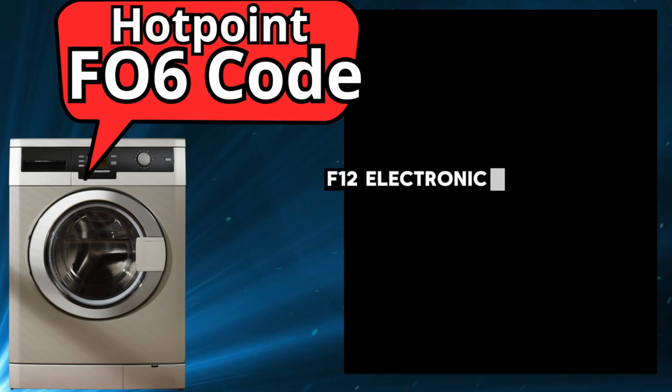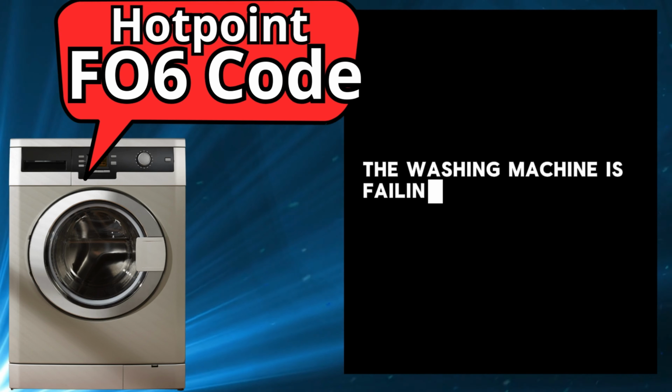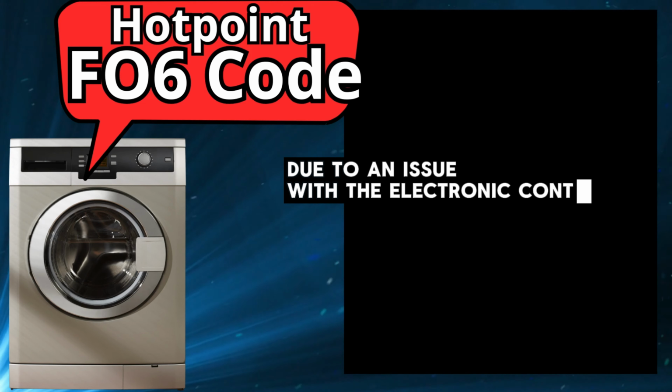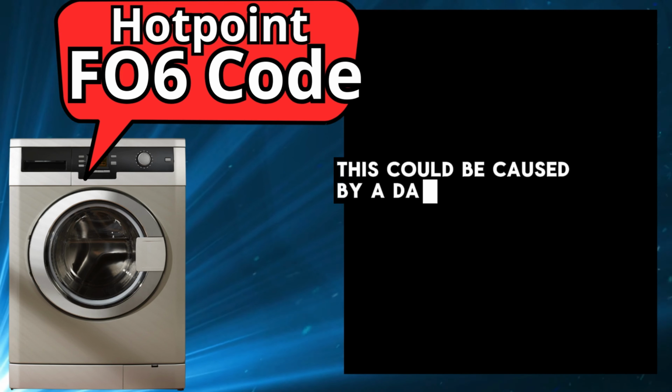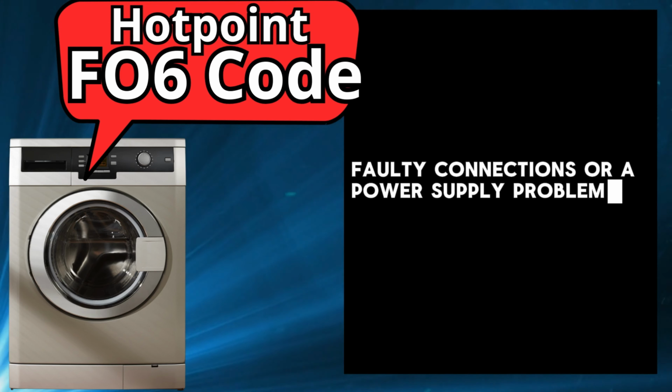F12, electronic control fault. If you see this error, the washing machine is failing to power on or operate correctly due to an issue with the electronic control system. This could be caused by a damaged circuit board, faulty connections, or a power supply problem.